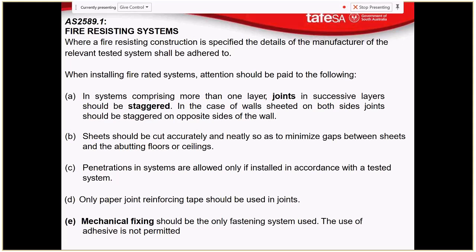This walling system, we're probably going to be around the 250 to 260 millimetre width, depending on our cavity between. And this system here, we're looking at around the 190 millimetre width. But in terms of acoustic benefits, we're going to have much better performance from this system and this system than we are from that.